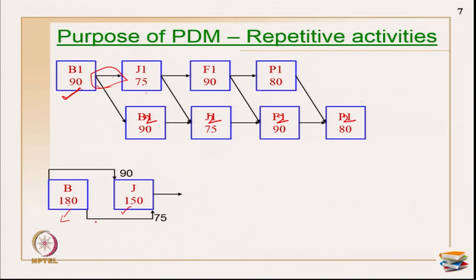Now same case, suppose if I don't put a finish, I can do my brickwork and joinery maybe also in parallel, which is not acceptable in this particular case. So what I have to do, I have to finish my brickwork at least before 75 days. So the 75 days is primarily coming from my joinery, which is also settling with my finish. So brickwork is fully completed, and for the last joinery there may be a 75 days lag in order to finish my joinery. So once I am fixing my start relationship and finish relationship, the complete representation of both the activities is really done.